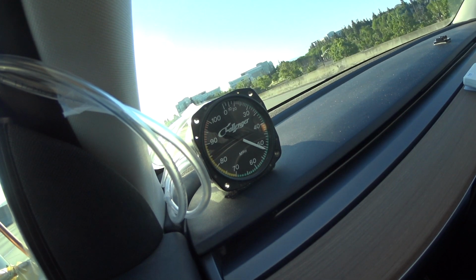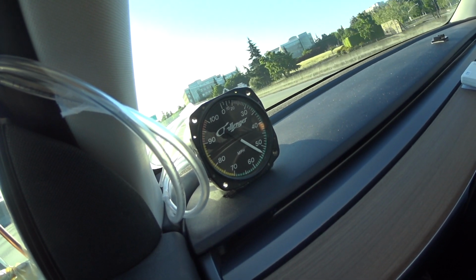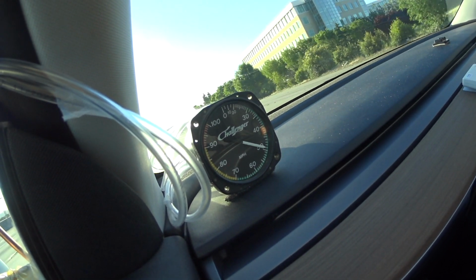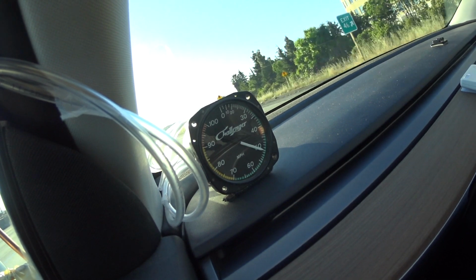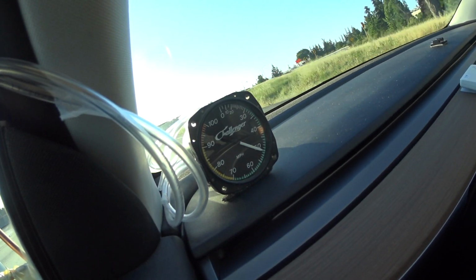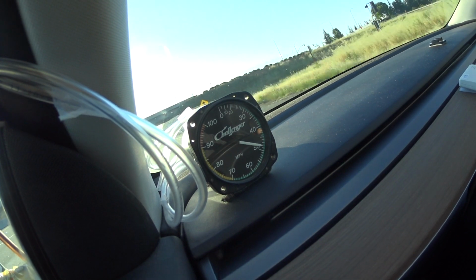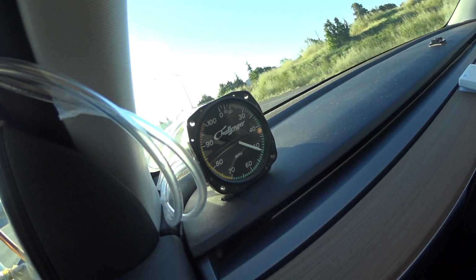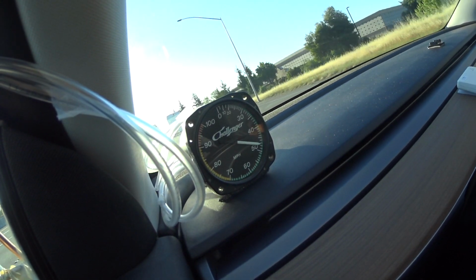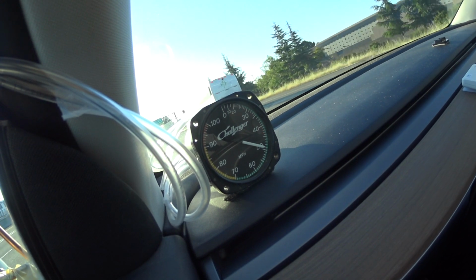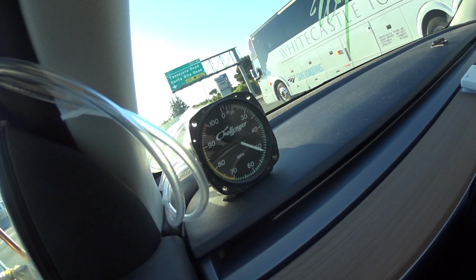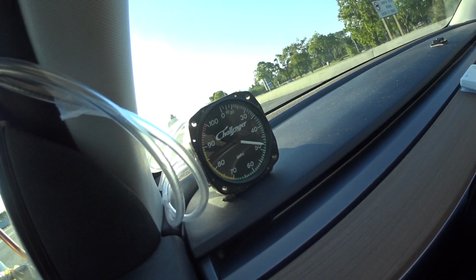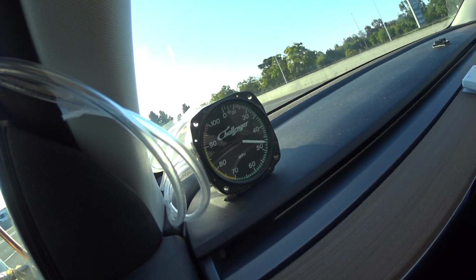So I ran this for a couple of miles and saw that the ASI was fluctuating between around 45 or so to 60 or so miles per hour, even though I was anywhere between 65 and 70 miles per hour. So not particularly accurate. One of the things could be that I'm following another vehicle, and I realized later that that has a huge impact on the indicated airspeed, even though the car is going at the same speed continuously. It's just that the air is disturbed to the point that it's not recording the speed very well.